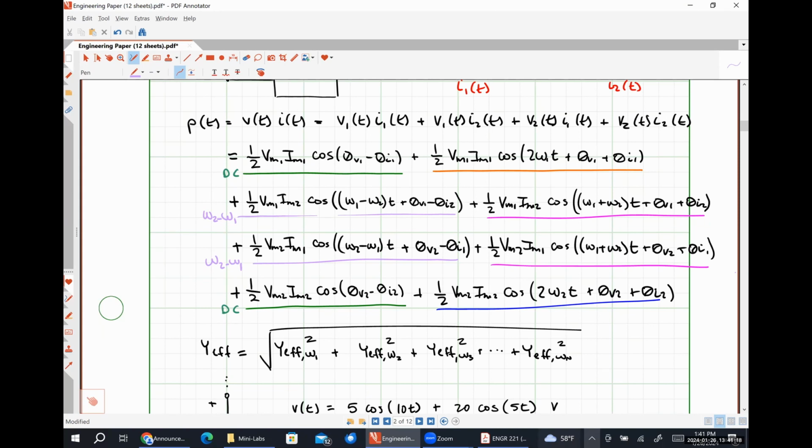So the short answer is, what if I connected 2 different analog wave function generators in series and set them at 2 different frequencies? That would be one way to do it. It's a dumb way to do it, but that could be something, right? So where you see circuits that operate at multiple frequencies most often in real life are radios and things like that, where there's usually going to be some DC stuff. Then there's going to be the frequency that your message signal is, and then the frequency that your carrier signal is.